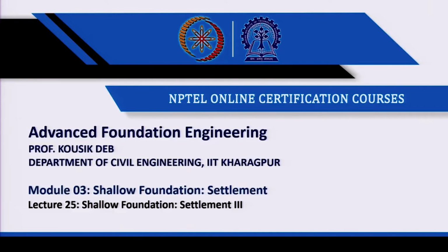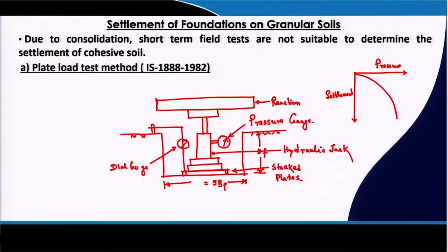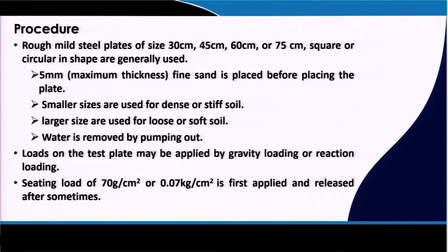So, last class I was discussing the plate load test. I have discussed that ultimately we will apply pressure and measure the settlement, and we will get the pressure versus settlement curve, and that curve will be used to calculate the bearing capacity or the settlement of the foundation.